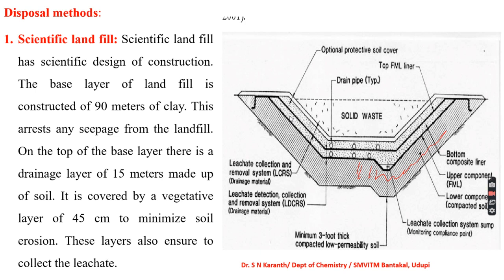This is the most popular solid waste disposal method, in which the garbage is spread into a thin layer, compressed and covered with soil or a plastic foam. The bottom of the landfill is covered with an impervious liner, which is usually made up of several layers of thick plastic or sand. Here, what I observed is that sand or clay is used, three layers of clay.